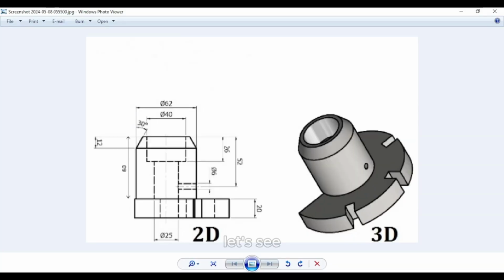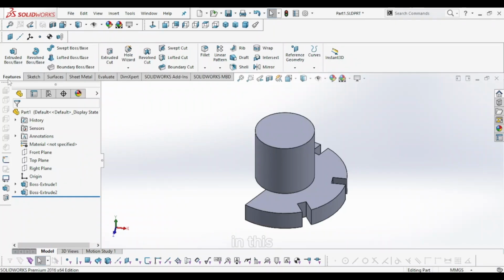Now let's see what else we have here. So there's a chamfer at a 30 degrees angle. This will be a new feature we'll be exploring, and I'll be explaining it in a bit. In this feature tab, you can see there's an option of a fillet, but we don't need a fillet, we need a chamfer. So just click on the drop down menu and you'll see a chamfer feature here.